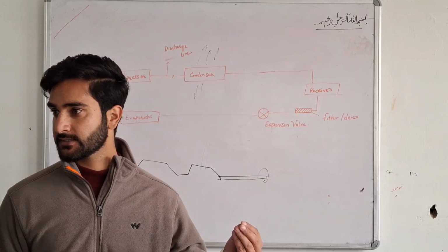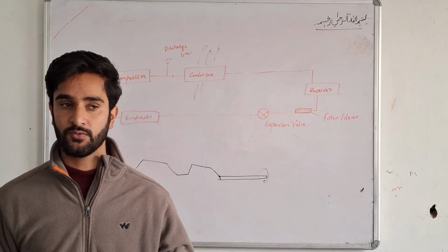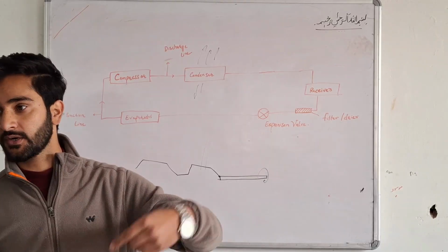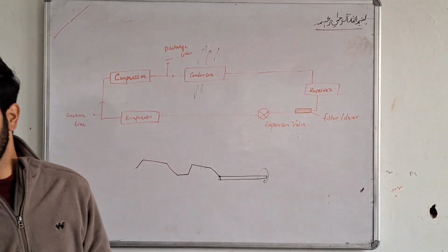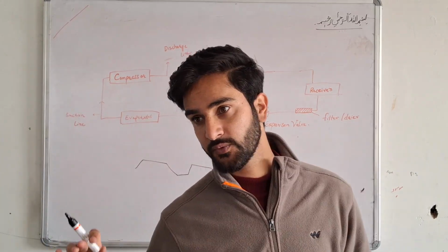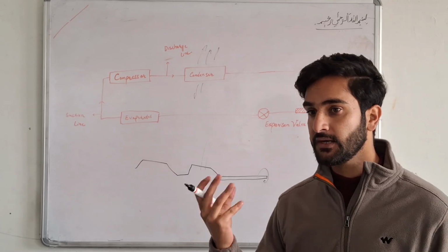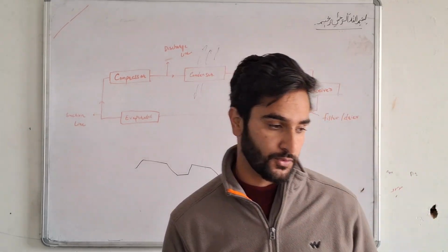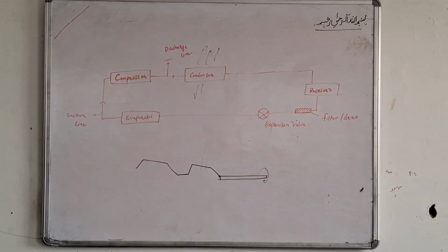Whenever the compressor is damaged, due to high voltage or something else, it cannot be repaired manually unless its weld is broken off. We have to destroy its joints, we have to remove its welding, and afterwards we can repair its motor. So it is impossible for this kind of compressor. I'll show you. This is a type of compressor I'm showing you here.